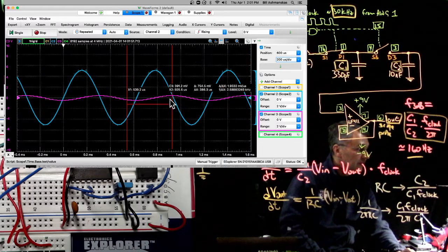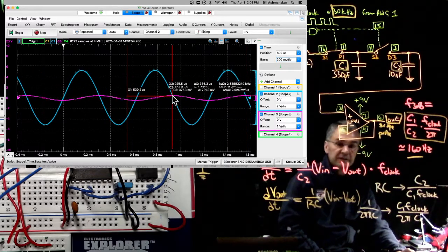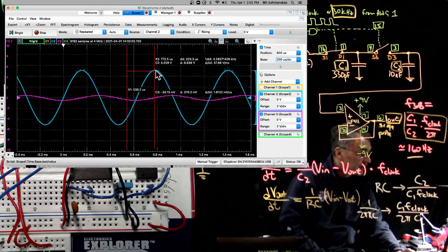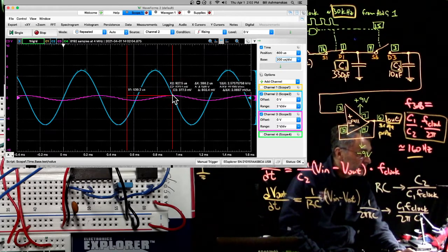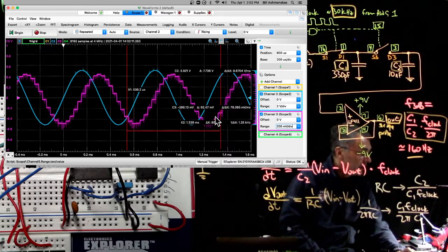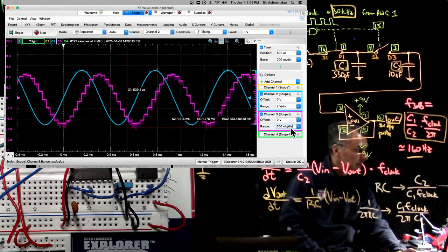And we should see an amplitude of something like 1/10. So this is like 5 volts amplitude. This should be something like 500 millivolts amplitude, I think. Let me blow this up. Hey, that's pretty decent. I blew this up by a factor of 10.